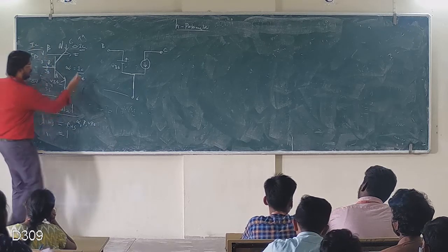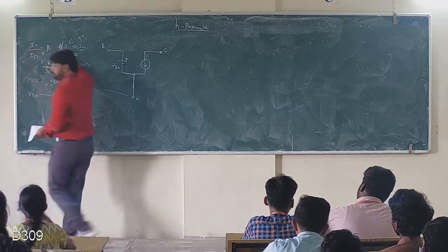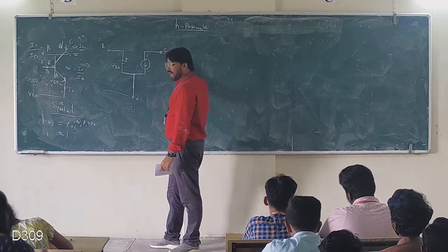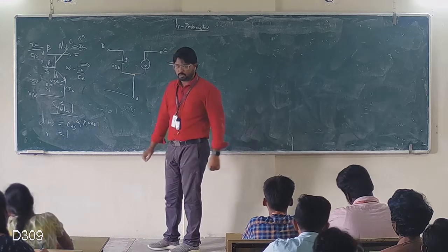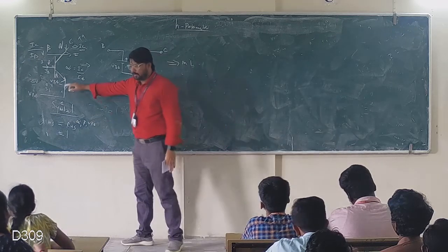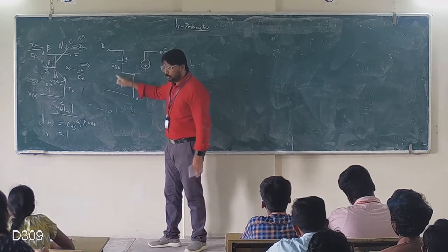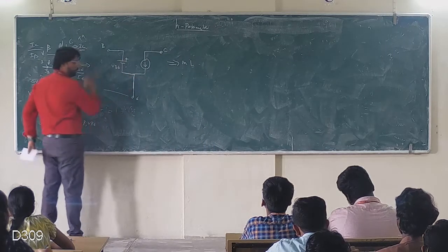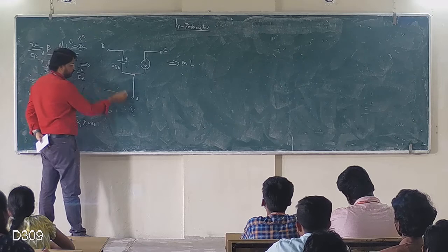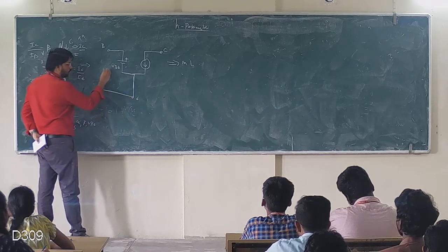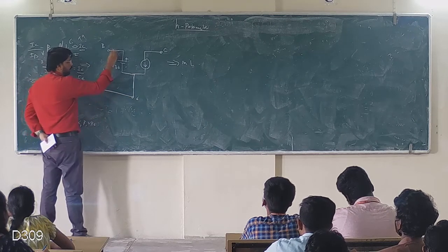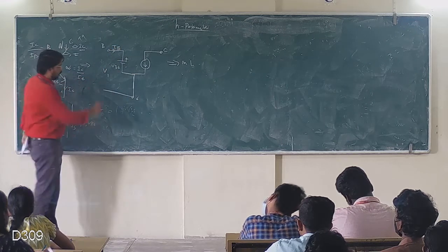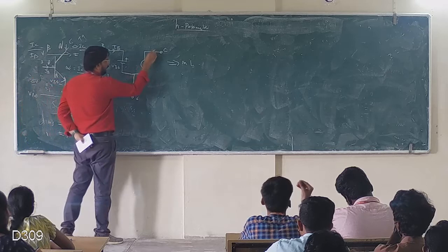So I am trying to convert my symbol into equivalent circuit. Then I try to convert that into mathematical model. You got the point? Symbol into equivalency, right? What is this? Barrier potential. What is that? Voltage source. So V1 is my voltage. Because of that, there is a current. IB is going, right? Because of change in V1, there is a current flowing.